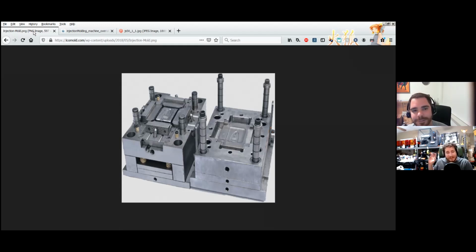And here's a really cool thing. This is not the first one that we've done for them. We did a different revision that they were sold on. They said, we did all of our testing, it should be fine. We gave him the 3D printed part. He said it worked for about 10 seconds and then it basically exploded. Because these are vibratory feeders. This whole part is vibrating at crazy amounts. And he said, I'm so glad we did this test, because had we spent the money and got this milled out of Delrin, it would have likely also broken. Delrin has similar properties to the material that we're making this out of, which is PETG.